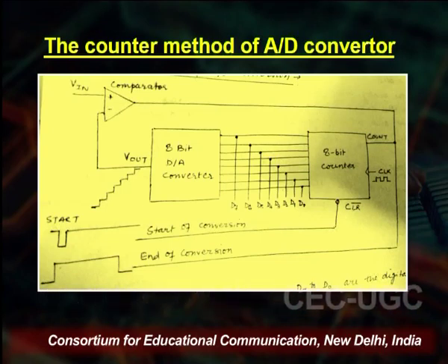As you can see, where is the analog signal being fed? The analog signal is being fed to the op amp, and we have fixed the other input of the op amp as our reference. If we look at the op amp in isolation, then we see that it will change state only when the reference voltage is exceeded by the input, or the reference voltage remains the same and the input becomes less than the reference voltage.